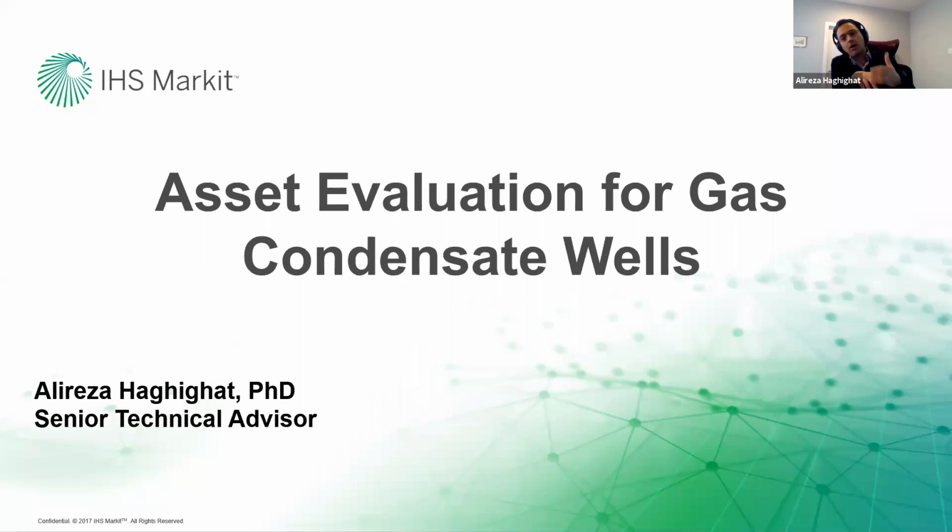If you are above the dew point or below the dew point in the gas condensate reservoir, this really affects your condensate production. If you are above the dew point, you can bring the gas to the surface, and at the surface you decrease the pressure and you are going to produce a lot of condensate.